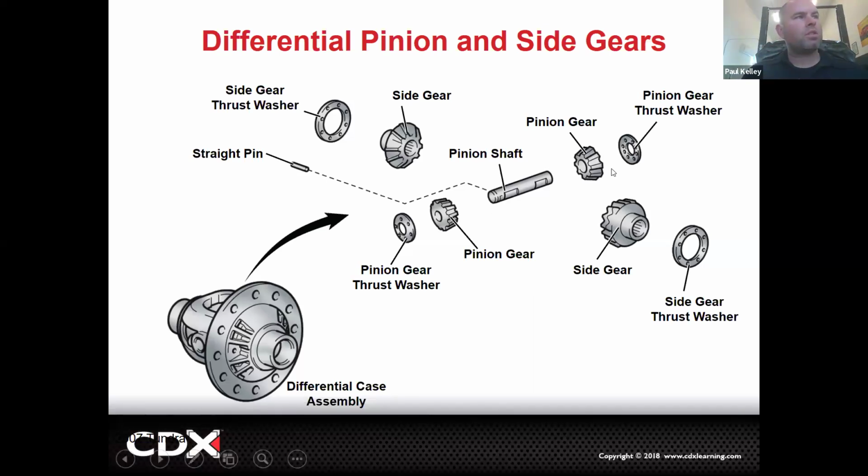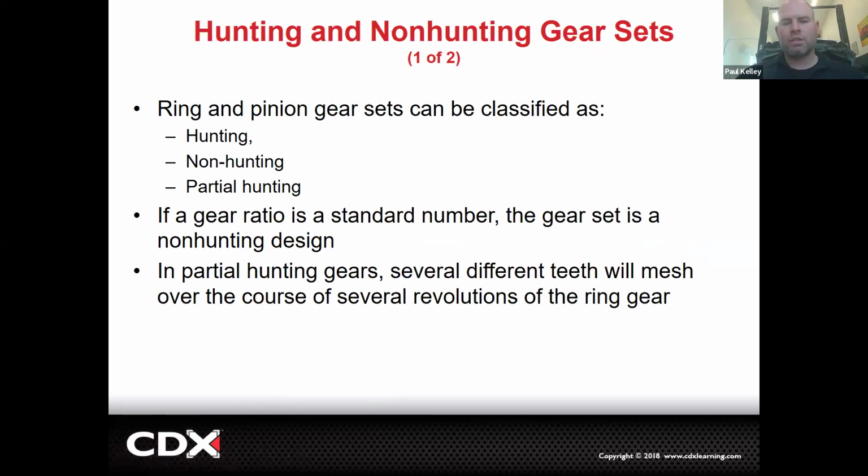Cool. So these differential pinion gears really drive the side gears, but what drives the differential pinion gears is this pinion shaft. So the pinion shaft not only holds them, but it's also what drives them. What drives the pinion shaft, you ask, is the actual case, because the pinion shaft is slid through the case right there. Okay, so there's a lot to visualize. You absolutely will need to have watched that video. Cool. And then sometimes the pin is driven through the pinion shaft, and other times it's a bolt, and we're actually going to show you some of that service.